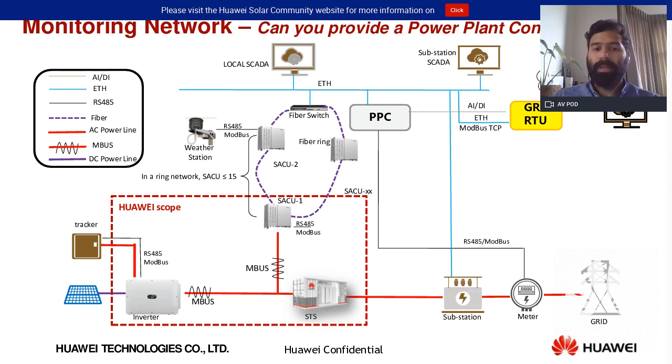So the PPC normally will be provided by your monitoring company, which most of you already have contacts with. For those of you that are not familiar with what a PPC is, it is an interface between the DNO and your site. It will be the main controller, the main brain of the site, and it will allow the DNO to, let's say, manage or control your site and give instructions like the rate or injection of reactive power.